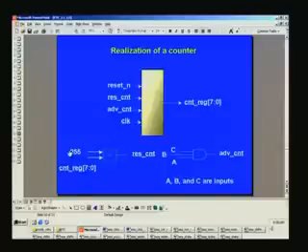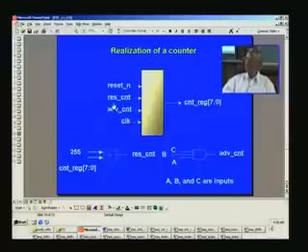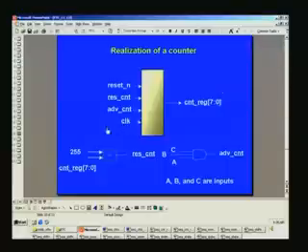This setting point can be changed if you wish. There is another setting here, and you can advance the counter when this condition is satisfied, that is ABC being 1 each, and of course there is a clock which is reckoned at a positive edge, and finally there is an 8-bit counter whose output is displayed here.